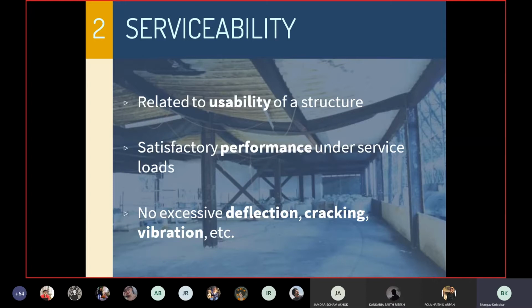Now, wind or earthquakes have their own frequencies, and buildings or say bridges have their own natural time period, or their own frequency. What it means in very raw terms is that a building that is short would have a very small time period as compared to a building which is very tall. Meaning that if a tall building is subject to lateral forces, say it sways, it will take longer to get back to its original position as compared to a building that is short. I hope this is very simple to imagine. So a taller building has a greater time period or a lesser frequency.